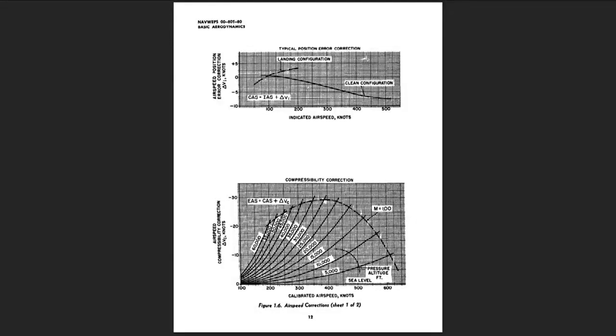3. The equivalent airspeed, EAS, is the result of correcting the calibrated airspeed for compressibility effects. At high flight speeds, the stagnation pressure recovered in the pitot tube is not representative of the airstream dynamic pressure, due to a magnification by compressibility. Compressibility of the airflow produces a stagnation pressure in the pitot which is greater than if the flow were incompressible. As a result, the airspeed indication is given an erroneous magnification. The standard airspeed indicator is calibrated to read correct when at standard sea level conditions, and thus has a compressibility correction appropriate for these conditions.